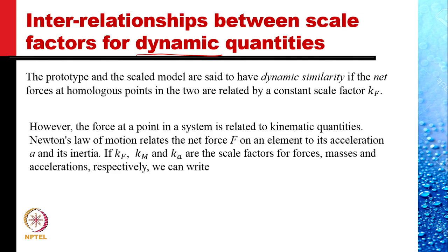However, the force at a point in a system is related to kinematic quantities. Newton's law of motion relates the net force F on an element to its acceleration A and its inertia. So if Kf, Km and Ka are the scale factors for forces, masses and accelerations respectively, we can write force is equal to ma gives us Kf, the force scale factor, would be Km times Ka.